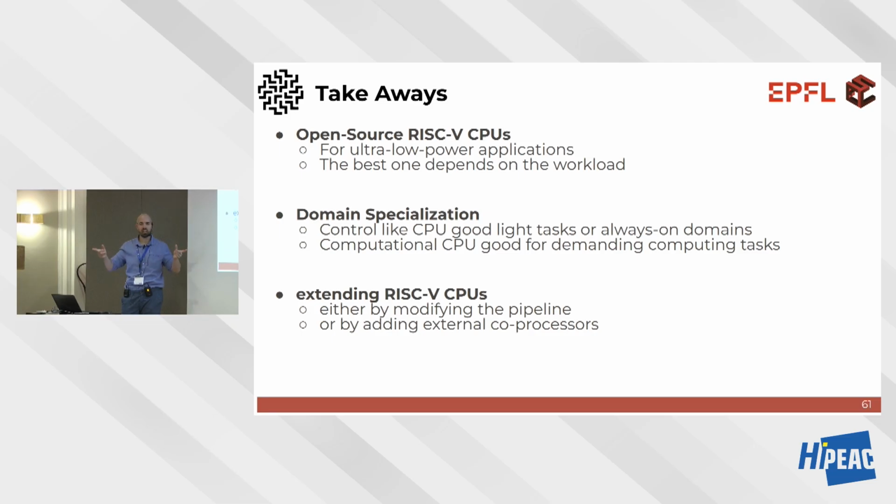That's why you saw the vectorial adder and vectorial comparator. Those are inside the CPU. Or, to decouple the CPU from the ISA extensions, you can do it outside with another coprocessor through the X interface. There are trade-offs, but definitely it's easier if you do it outside.